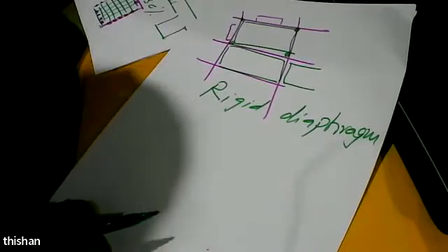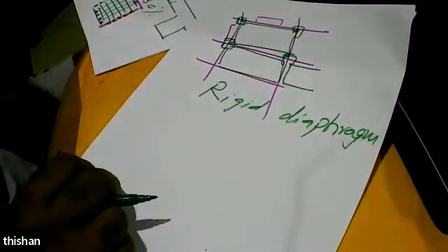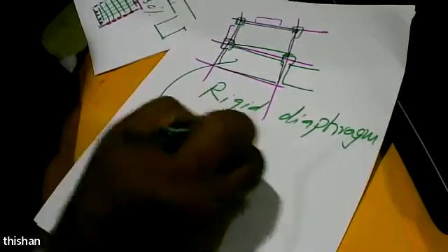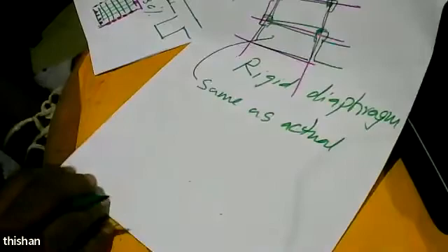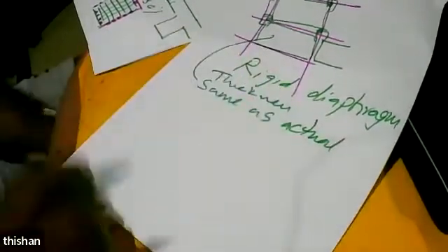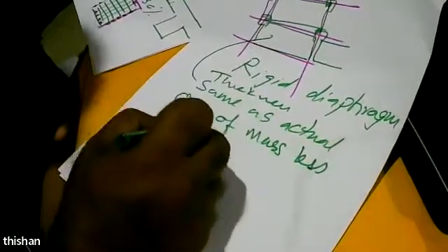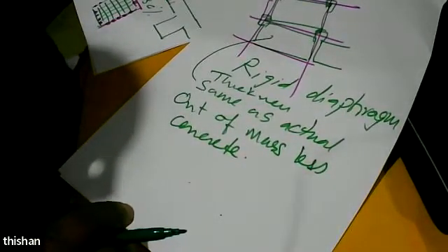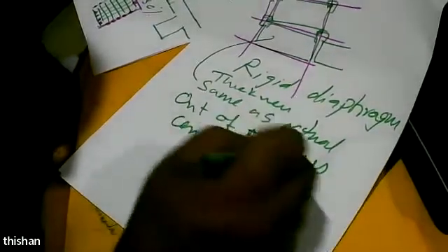But whereas the moment you actually represent each panel as a panel of equivalent stiffness, connected only at the corners, with thickness same as actual, but out of weightless concrete.